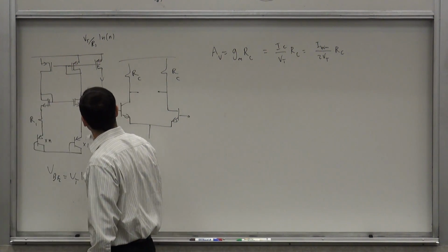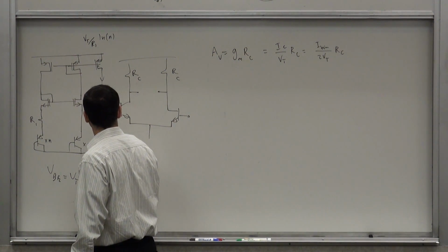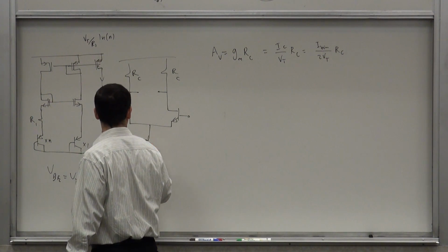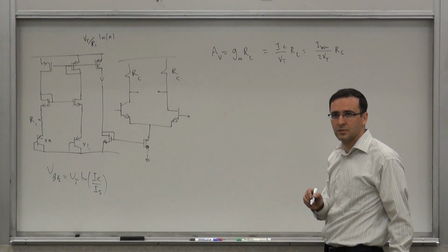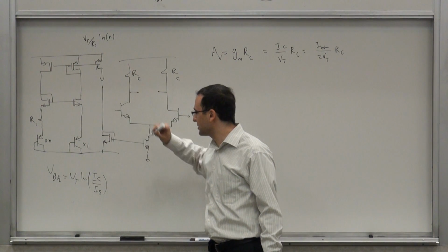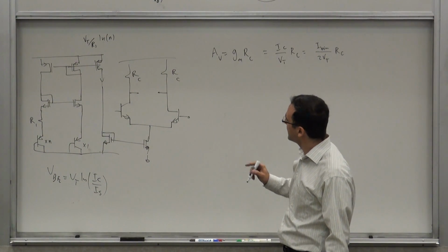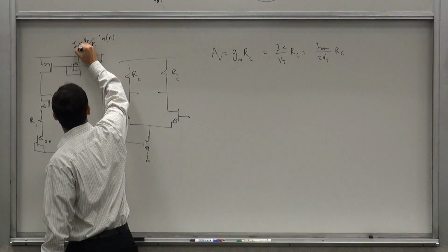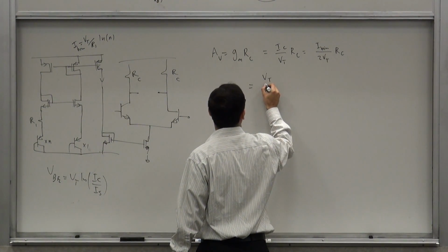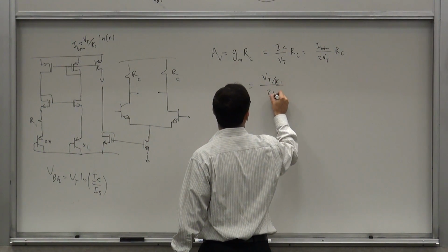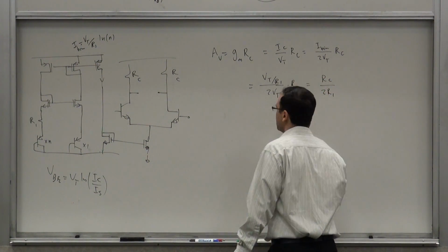Okay, so this is the PTAT, and then I need to bias this somehow with that, so I can use this one, bring it here, and do that. So what's my gain now, if I use this reference? Let's say these are ratios of 1, you could change those ratios later. So this current is the current I bias. If I plug that into here, what do I get? I get VT over R1 divided by 2VT times RC. Therefore, this is RC over 2R1. So that's my gain.